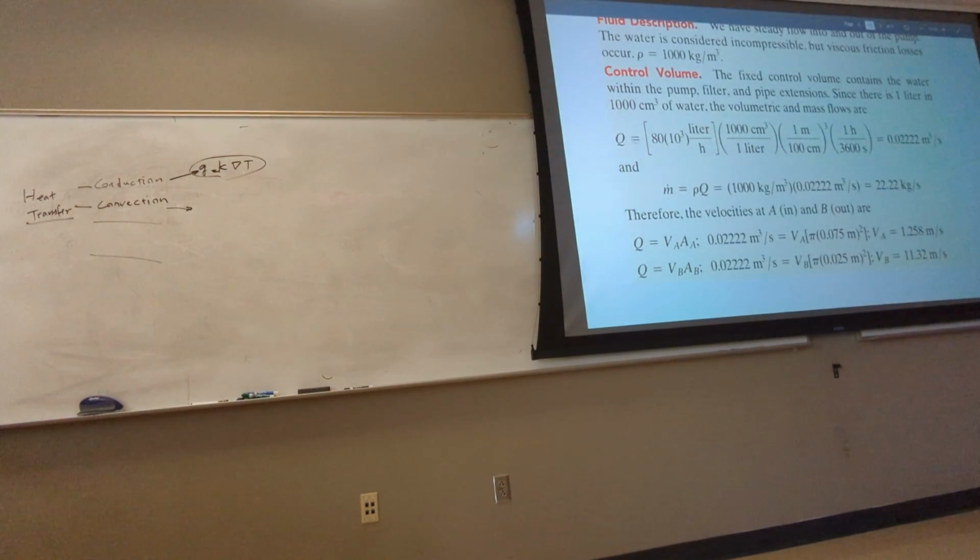Based on, he first converts meters per hour to cubic meters per second. You see that? You have to do that. Why? Because when you substitute this in the equations, everything should be meter, kilogram, second. And then from that, he finds the m dot.